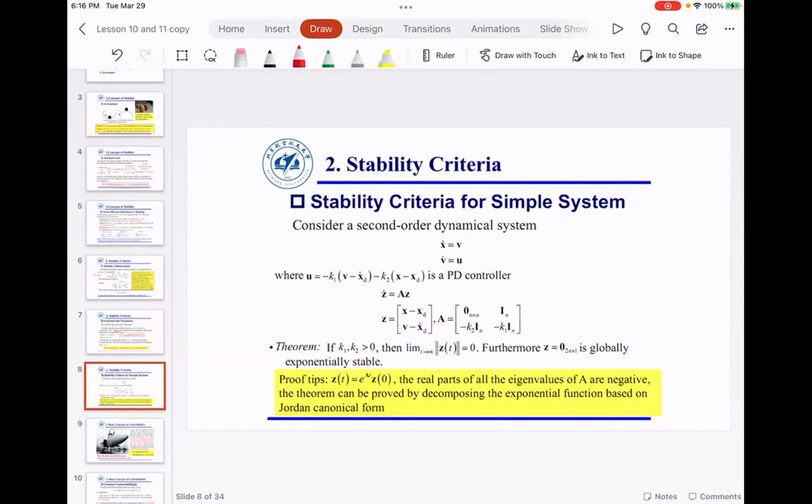The stability about the fixed point, which means it's in level flight, is called the trim condition. So the aircraft is trimmed, which means the aircraft is in steady state, level flight. Or you can have the stability about the periodic solution, which means the aircraft is going forward and backward, and then even if there is a disturbance, the aircraft continues to follow the set trajectory, and gradually the disturbance is minimized.